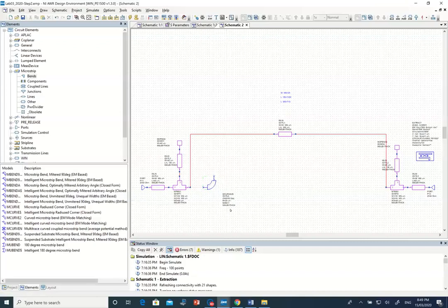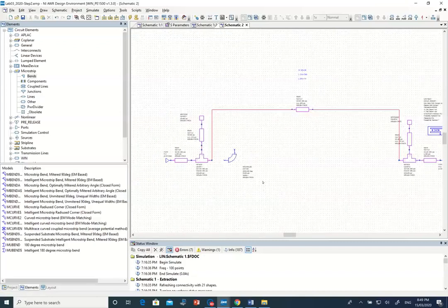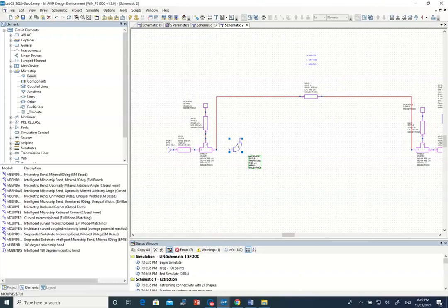Okay, and then I want a similar bend. I copy it on this side and then right click so that it changes. So that's one, and then I also want something like a small microstrip line here. Then I don't need this, so I'll just delete these outlines.